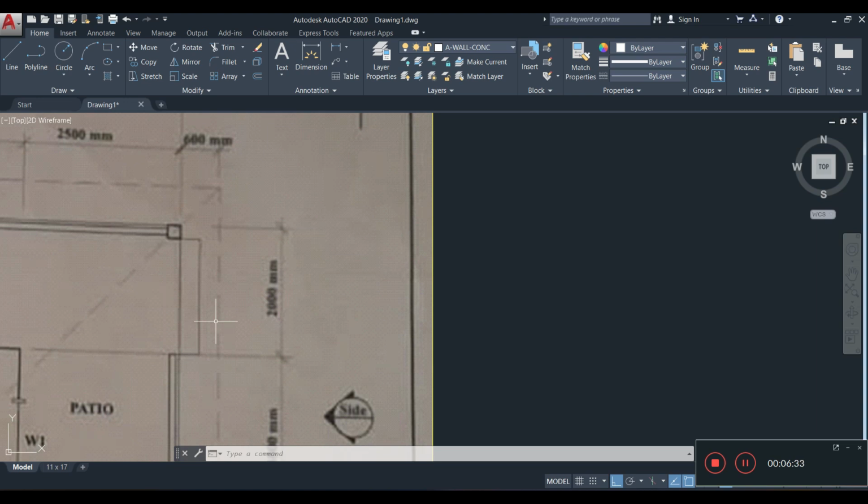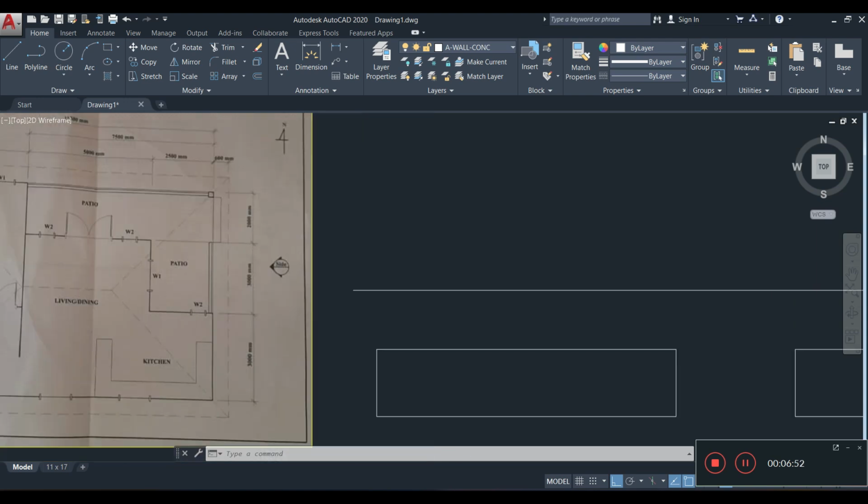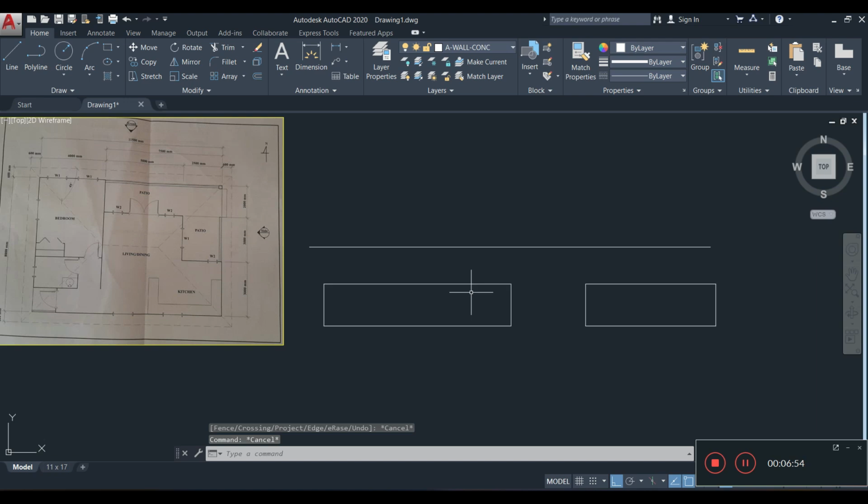If you look at most houses, you realize that the roof does not stop flush on the wall in most cases. It hangs over, so when it rains, the water does not run down on the wall. It goes beyond the wall and then falls on the ground, just because the roof is extended a bit further from the wall. Now you can see here it says that measurement there is 600 millimeter. So what I can do is simply draw a line out 600 millimeter like this. There's various ways as long as you get that 600 millimeter.